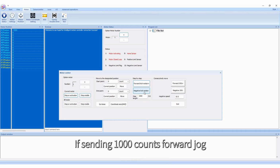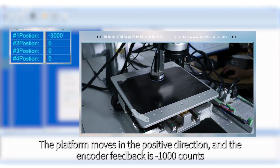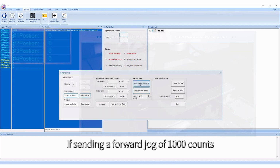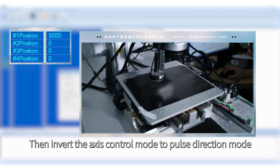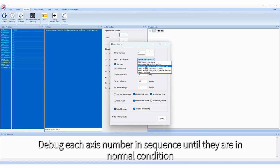If sending a 1000 counts forward jog, the platform moves in the positive direction, and the encoder feedback is -1000 counts, then you need to reverse the encoder. If sending a forward jog of 1000 counts, the encoder feedback value is 1000 counts, but the platform moves in the negative direction, then invert the axis control mode to pulse direction mode. Debug each axis number in sequence until they are in normal condition.